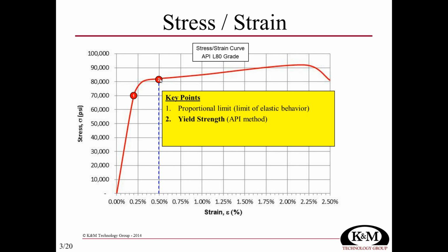Notice that just because we're saying that that's the minimum yield, the pipe has actually already yielded at that point. In fact, we've permanently deformed the pipe. We've got into the plastic region down here at 70,000 psi. It's not a lot of plastic working, but there is some. There's not a lot of strain, so it's just at the beginning of that cold working process.